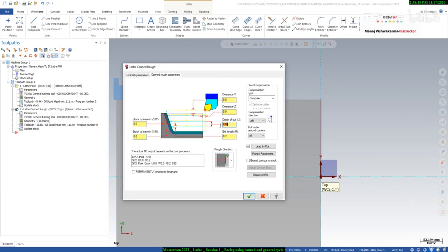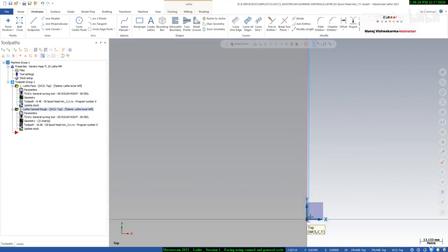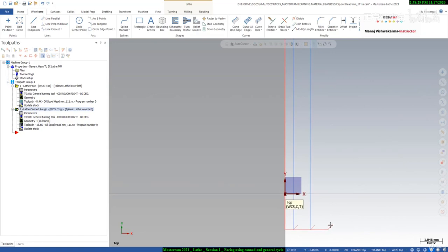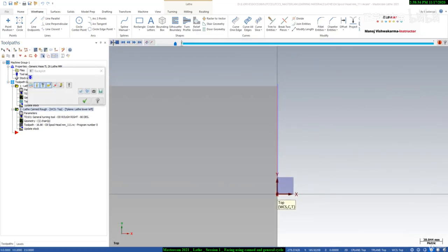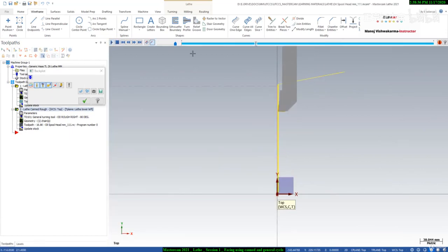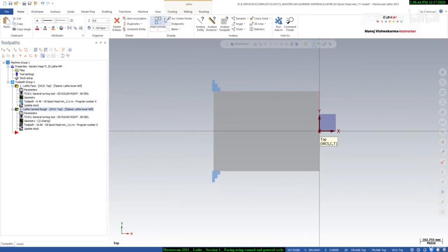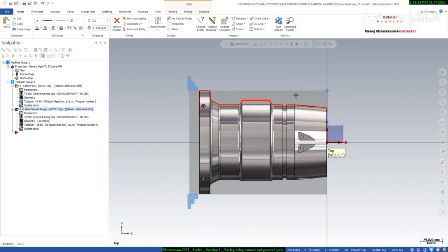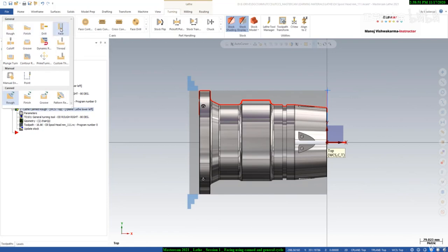So we have given 0.8 mm of cut. Okay, so you can see 2 passes created with the 0.8 step over like this. So I will show you the backplot also. Okay, fantastic, done. So we have covered facing toolpath using general cycle and facing toolpath using canned cycle.